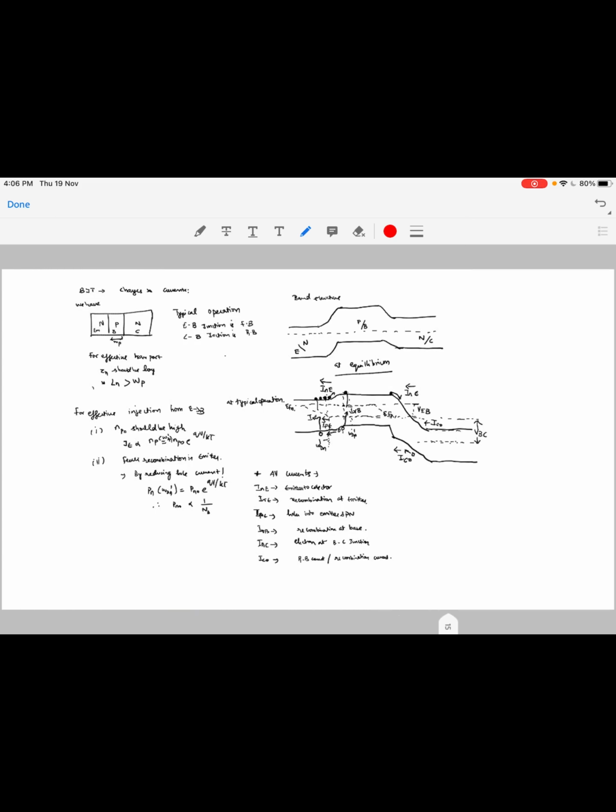Next, we talked about the BJT. A BJT is nothing but PN junction diodes connected back to back. But we saw that the main purpose of having such a structure is that if we are able to control the electron injection into a depletion width, then you can basically have a constant current source whose value you can change. Because you typically want to work somewhere here, but it is this current, the constant current characteristic, which you would like to change by changing the emitter injection. And so this is basically what was required, and that's when the BJT actually started to be used.